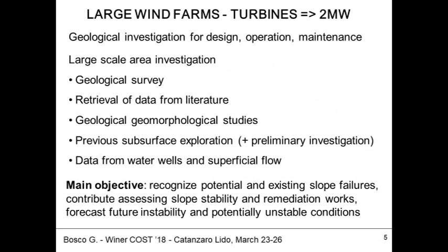Very helpful in this case is geological investigation, especially when we have instability problems, because it is easy to concentrate the subsurface investigation at one tower location. It is difficult to expand the subsurface investigation away from the tower for 2 reasons, operational and cost.